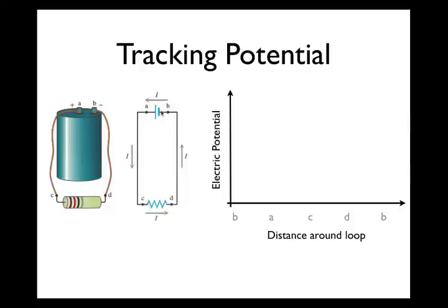So these two little lines that are parallel but of unequal length symbolize the battery. The longer line symbolizes the positive end of that battery, and so you'll notice the current, symbolized I here with an arrow, flows from the negative end of the battery to the positive end of the battery. It flows around the circuit, encounters the resistor right here, which is symbolized with this zigzag line, and then flows back to the battery. Wires, even though in reality they curve and go in all kinds of directions, are drawn as straight horizontal or vertical lines in most electric circuit diagrams.